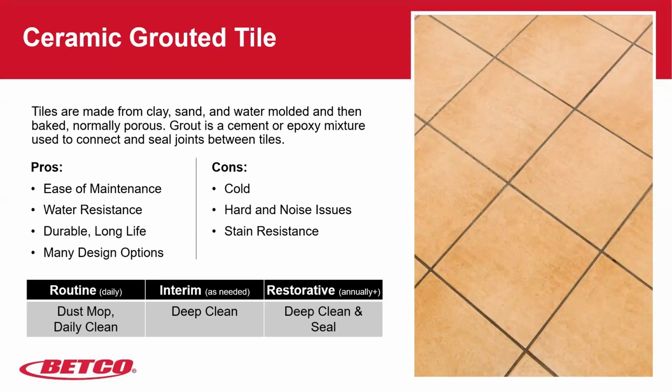But ceramic tile, for example, has ease of maintenance. It is water resistant, durable, long life. There are many different design options, and the cons are it's very, very loud. It's not a real stain resistant product, so you can stain it fairly easily. Dust mop, routine, interim, and restorative in the life cycle of floor care. Dust mop and scrub that floor. Deep clean, and then deep clean.